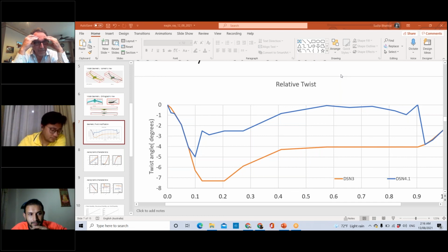The nose wheel on that airplane is actually the main gear, and the other gear are actually tail wheels. So there's two of them, but they're not carrying much weight. The nose gear is actually a main gear. It's a huge tire because it's carrying all the weight of the airplane. And it's holding the airplane at a very high deck angle because flying wings have difficulty in ground effect pulling the nose up that high. So it's all the same issues we're seeing.